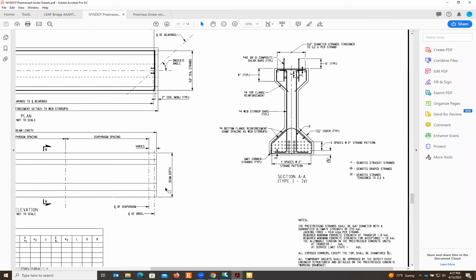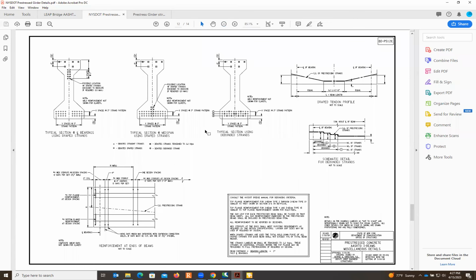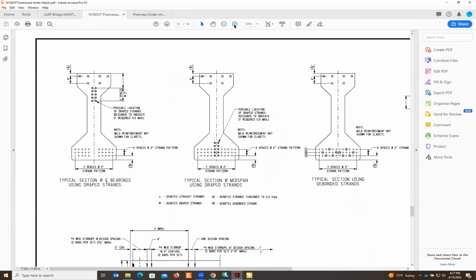So let's take a look at the next page. Okay, so those are the locations for the pre-stressed strand. So make sure those, when you do the design, match those locations well. And we also take a look at the locations of the draped strand right here. Seems that we can get a maximum of 5 pairs. So total 10 strands for draped strand.